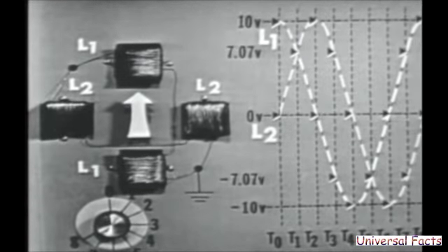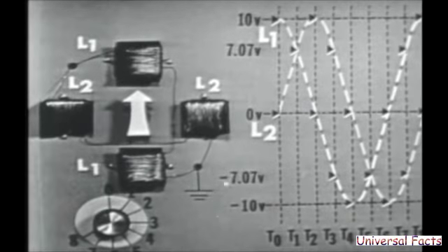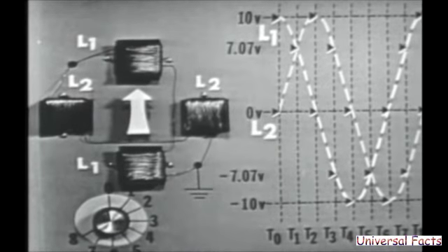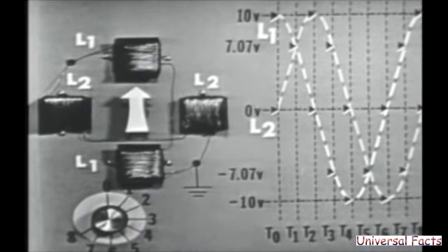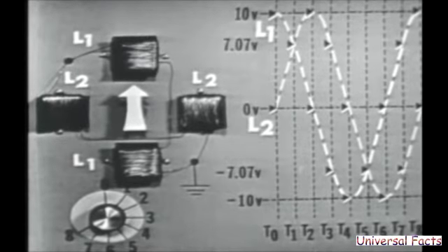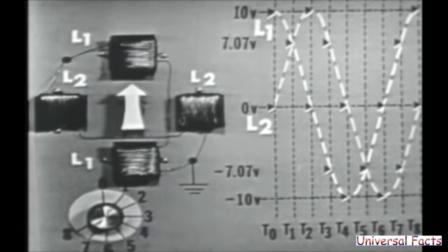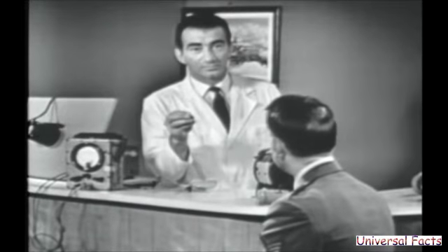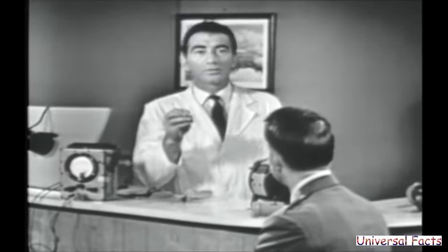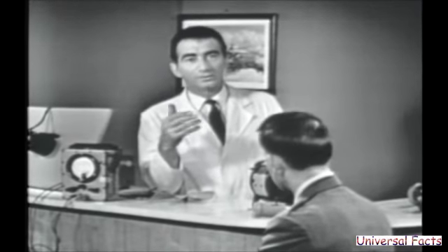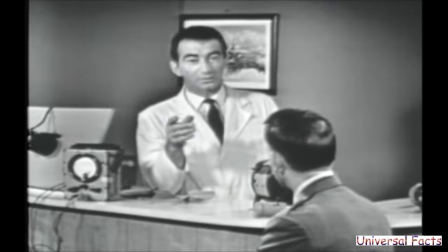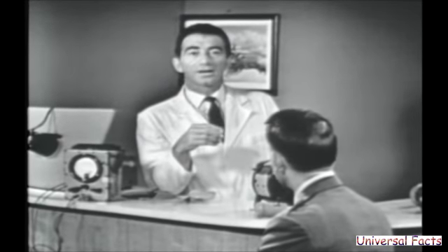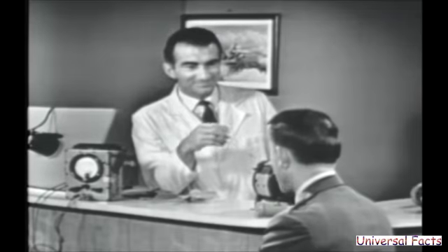I'm certainly glad you said that, a rotating magnetic field that induces a voltage in the rotor, causing it to become an electromagnet, which will follow the rotating magnetic field. Simple and rugged and economical. Right. The AC induction motor, because of all these facts, will be found very, very widely in your career as a technician. So study that TVI guide and learn all you can about it. I sure will. You will, too.